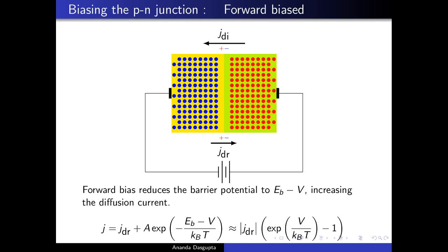One, reverse biasing the diode, trying to make current go from the N to the P, leads to a very, very tiny current. This tiny nature of the current is what we approximate often by saying the diode does not conduct any current in the reverse direction. Well, in a typical well-constructed diode, this tiny current can be anywhere from a fraction of a microampere to a few nanoamperes, a very tiny current.